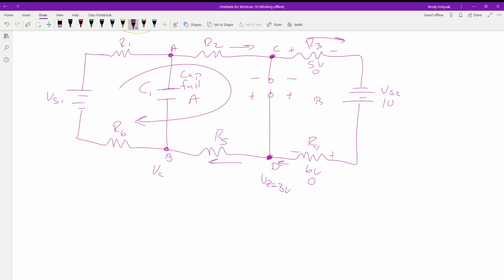I'm not saying that could be an option. I'm not saying that it's not an option. There's always the possibility of these. There's multiple variations of this problem thrown in there with different voltages, different polarities. The diodes turn different directions. It's different. Sometimes it's a Zener, sometimes it's not. Things like that. Again, it depends on what you're looking for. Like your power supplies, maybe you need to get it up just a little bit higher for your voltage. Use a germanium diode, you're going to have less voltage drop when you go through your diodes as a bridge.